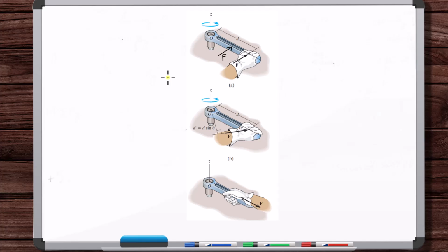Okay, so now, intuitively, what's the best way you would think to define this, a moment of a force, the tendency of this force to cause rotation about a point? Well, we think about a wrench. It's like if we said the magnitude of this force times this distance here from the point. And it's not just a distance, it's like that perpendicular distance, right? It's perpendicular to the line of action of the force. Because if you look here, the force is being applied at an angle. Well, now we don't want to say F times D. It's more of F times this D prime here, right?